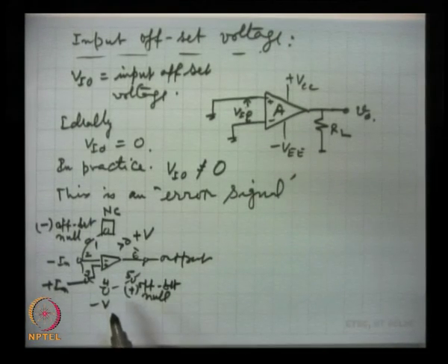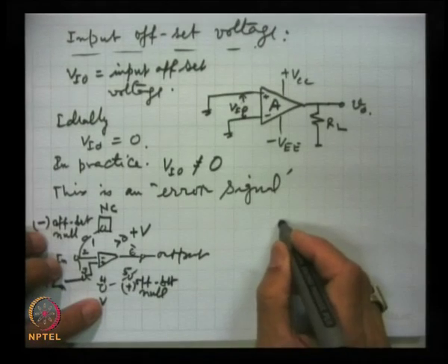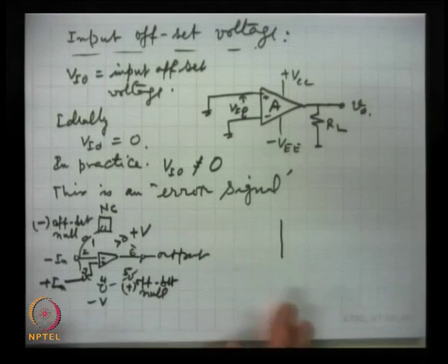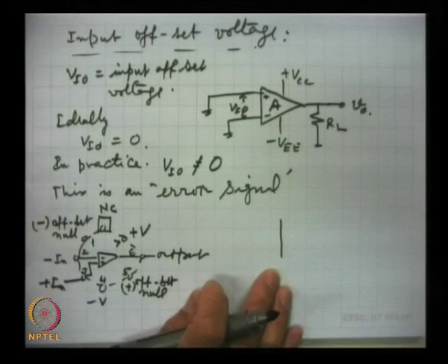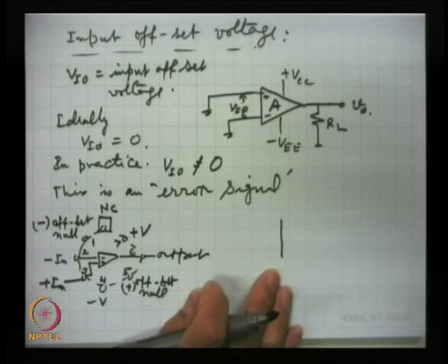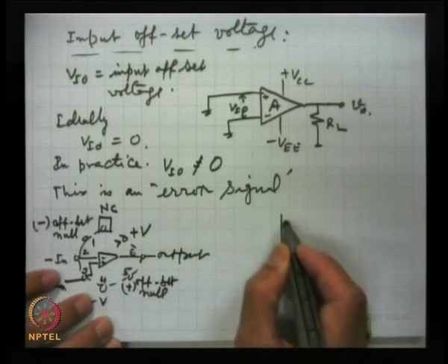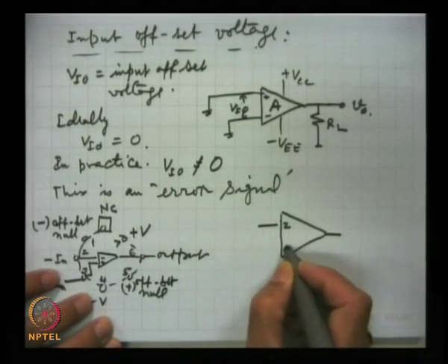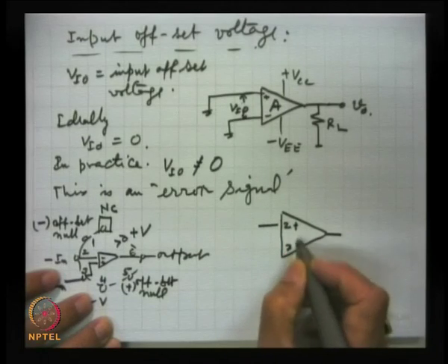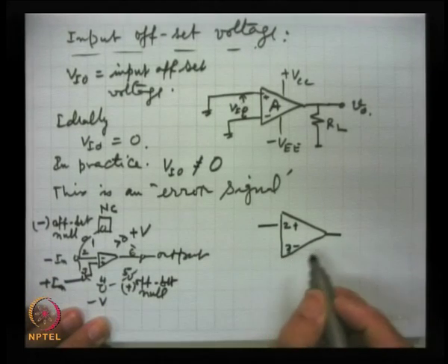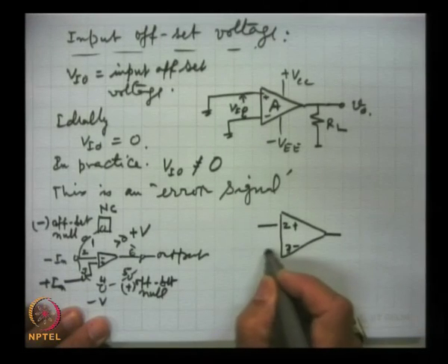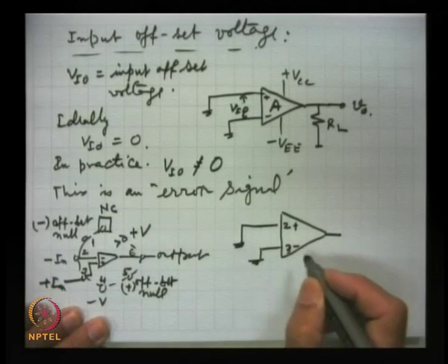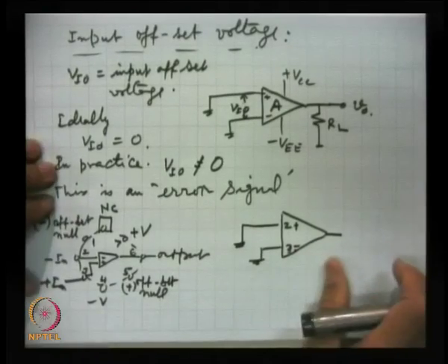And how we do that? Let us look here. This is done almost with every op amp. Whenever we want to use the op amp, we have to make corrective measures, and this is done invariably for all op amps. It is very simple. These are the two inputs 2 and 3. This is non-inverting, this is inverting, and both are grounded, and this is pin number 1 here. I draw this figure again.